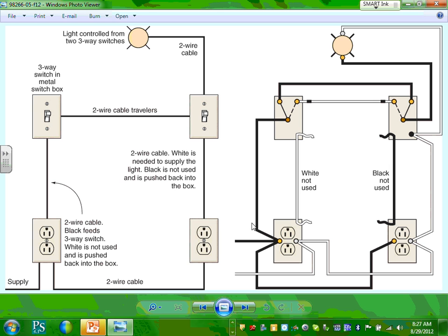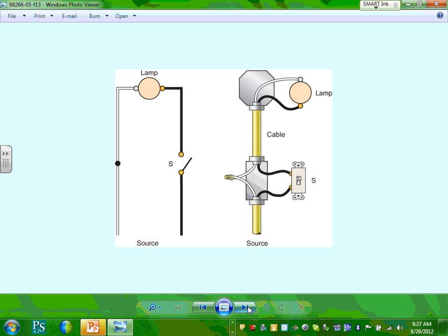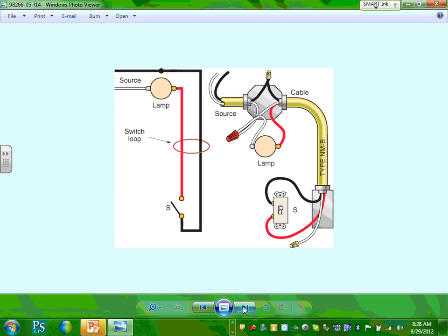Okay, this is about the neutral. Remember when we said your neutral? Okay, you can't end up with a black here. Look at that wiring mess. You always have to end up with wiring that takes the neutral and the circuit. Can you guys see the conductors with the same circuit in the same conduit? Can I have thumbs up, Chad? We got that one. Now I want to remind you, when we go to the commercial project and we start doing systems, you'll ask, well, how are you going to pull the neutral?